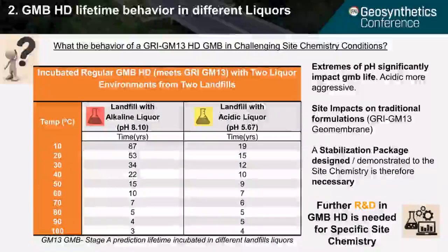In the Atterfield Lab, we have done research to understand how a regular traditional geomembrane will behave in different liquids. In order to evaluate that, we have created 2 samples of a regular HDPE geomembrane that meets GRI GM13 requirements, with 2 different liquid environments taken directly from 2 landfills, one alkaline and the other one acidic.